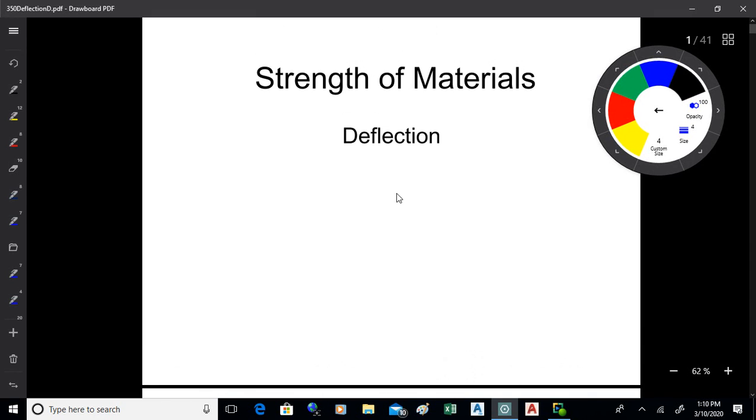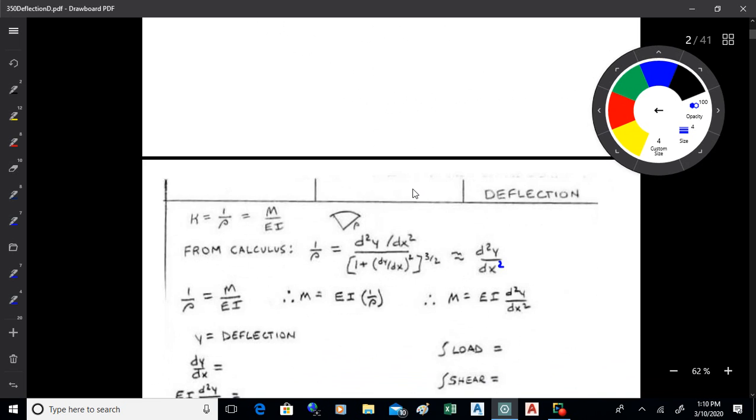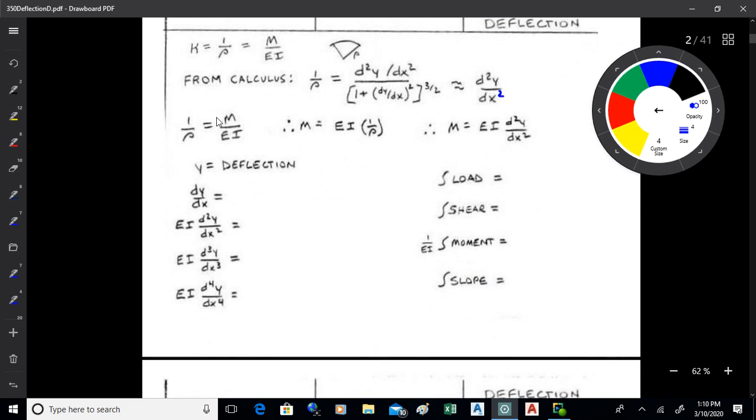All right, so we'll have a look at deflection here, and this is on 880, I think. This relates to how much a beam would deform when it's loaded, which is something you want to investigate a little bit. When we did the stuff with the bending stress, we came up with this relationship: the degree of curvature, which we call kappa, which is how extremely something is curved, is 1 over the radius of curvature. Keep in mind that r is the radius of a circle, rho is the radius of a non-circular curve, and that's equal to M over EI.